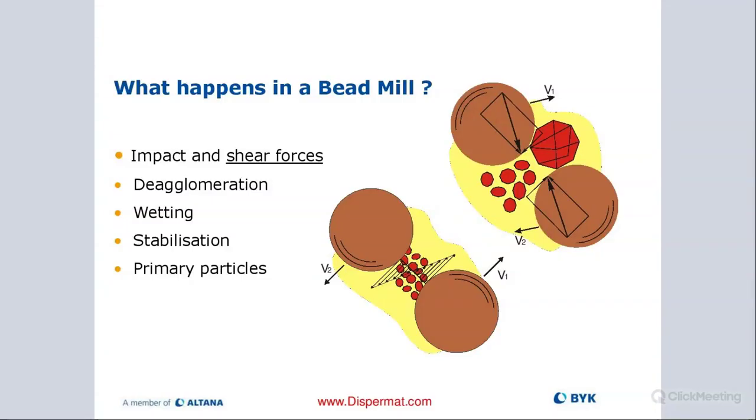The shear force is really the most important part here. It's not that you're likely crushing the pigment. This is not the objective. Most of your pigments obviously will get pushed away from the beads, and that motion is causing these van der Waals forces to break up, not really the crushing. We don't want to destroy our pigments. Now, there is some impact grinding that takes place. Obviously, if you have a very high bead loading, it's inevitable that you will crush some of the particles, but the objective is not to destroy them, but to really just separate them out and return them to their previous